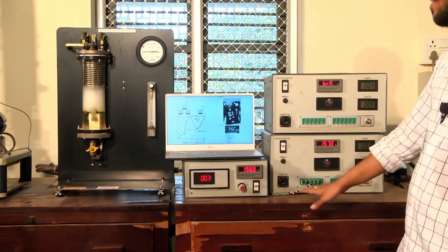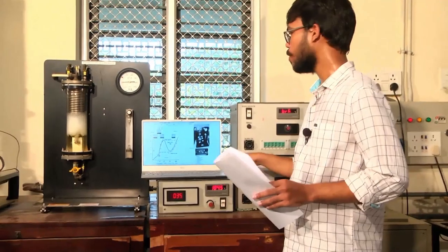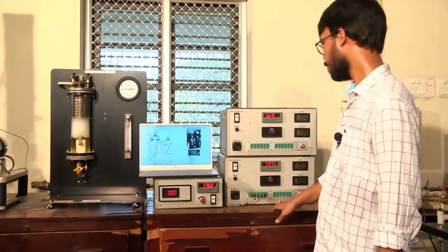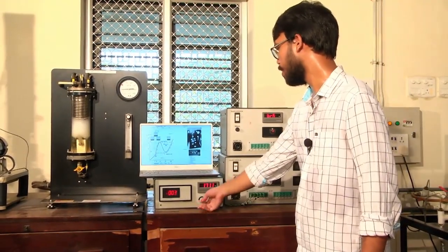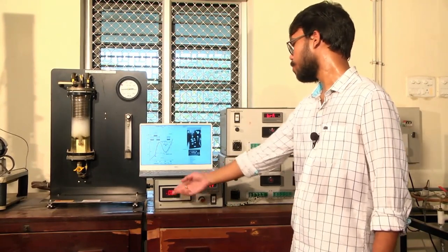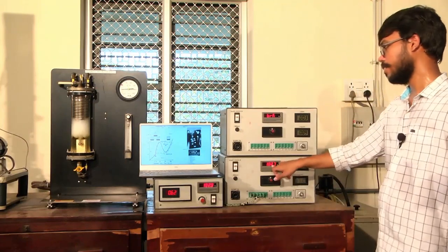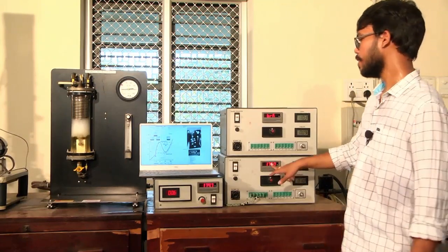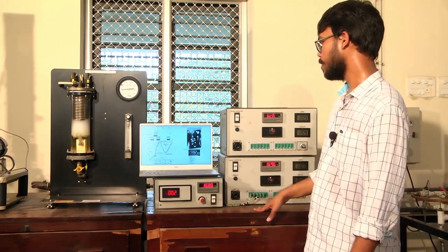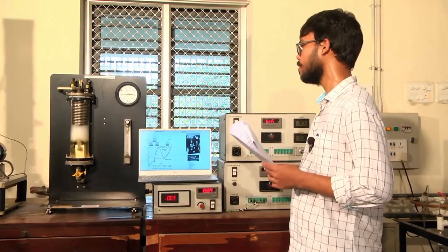So, this is almost the completion of the experiment. So, I am reducing the heat flux. Automatically it stopped the heater. You can see it came to 0. Because of the critical heat flux, the temperature also increased to 180 degrees. This is the critical heat flux point, and until now we have data to plot the pool boiling curve.